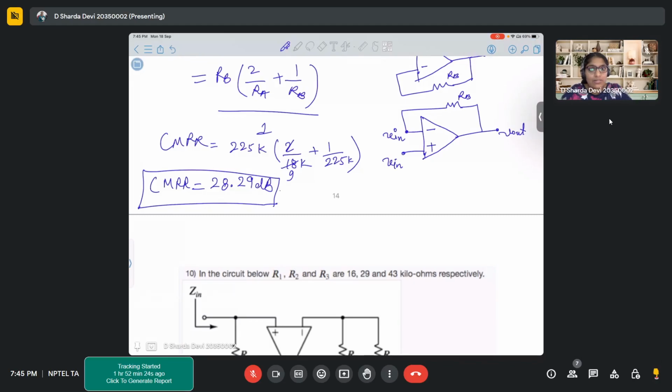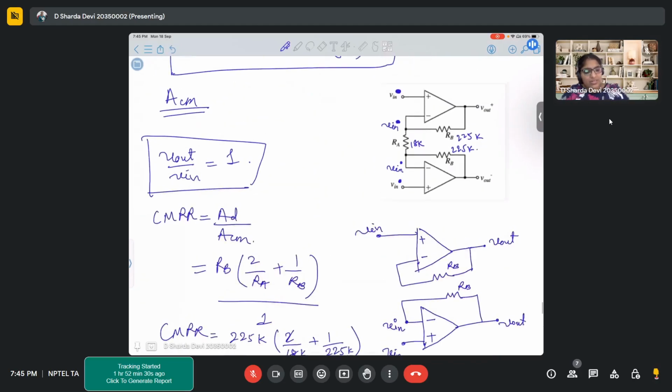Can you please tell us how it became an open circuit, ma'am, in the two op-amps? Mentioned already, right? The potentials across both terminals of a resistor are equal. So if the terminal potentials of a resistor are equal, will it lead to any current flow in that resistor?